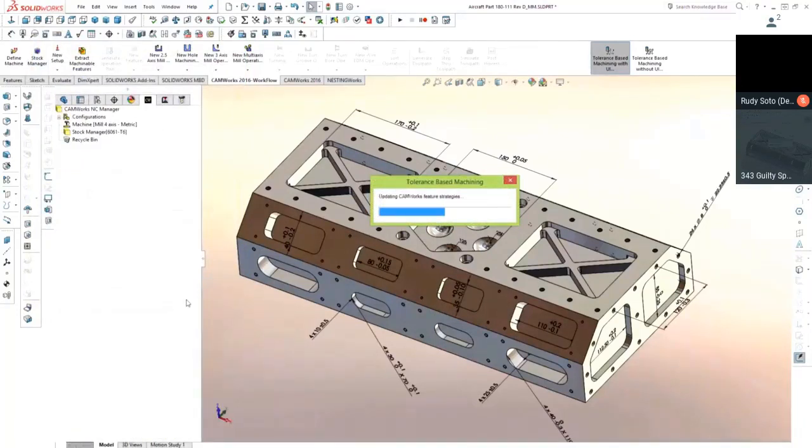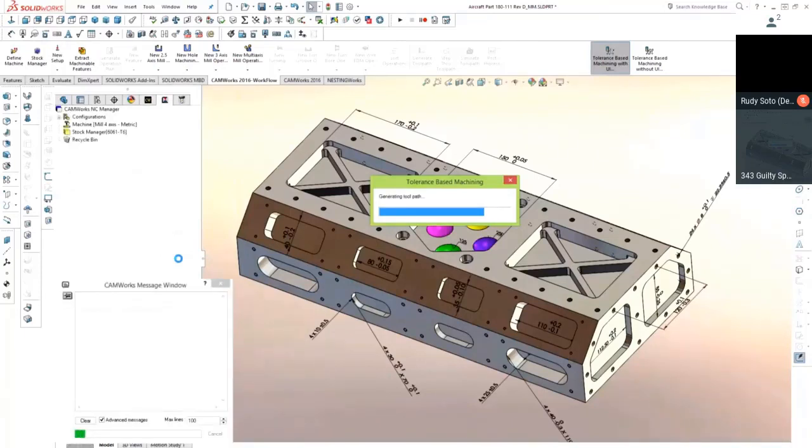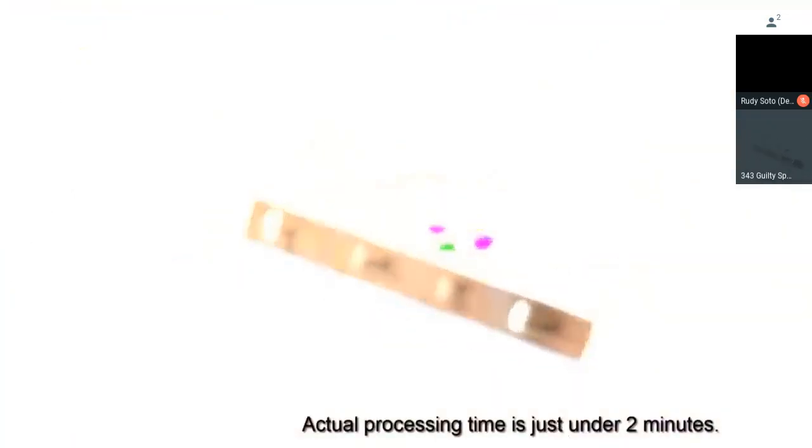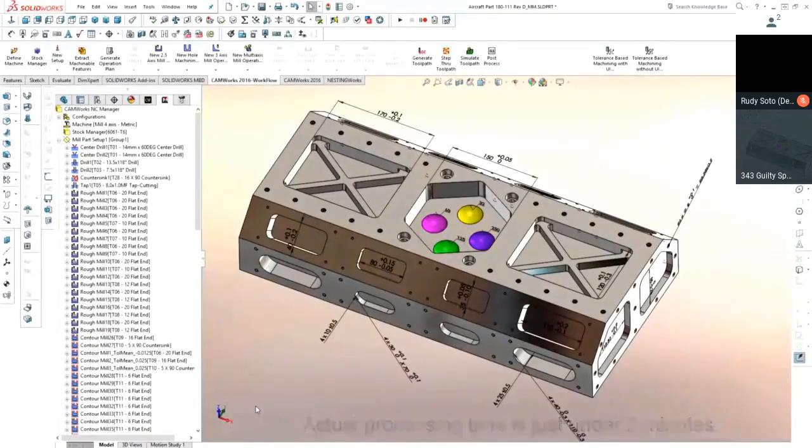Make sense? This tolerance-based machining, is it just leave material, clean up material like in the past or something? That's what this is. This is tolerance-based machining. The toolpaths will be like, you'll use a different size tool. You'll use finer toolpaths. You'll do more passes if there's a tighter surface finish, or if there's a tighter tolerance, automatically. That toolpath is written automatically in that fashion. It's written to grab a different tool. It's written to do more passes. It's written to do finer passes, automatically based on the tolerancing information from PMI. That's tolerance-based machining.